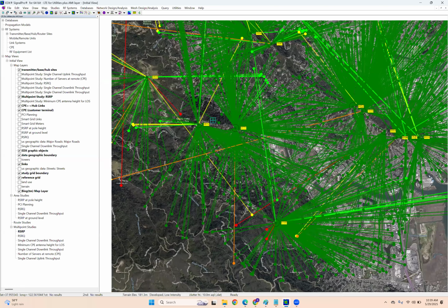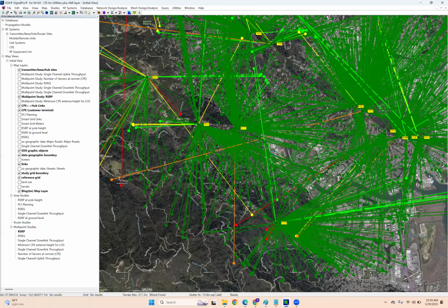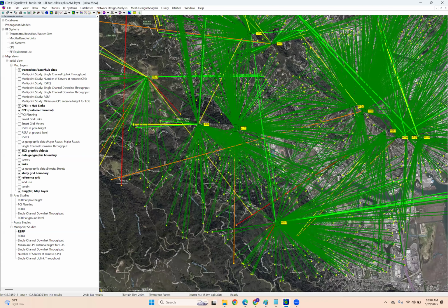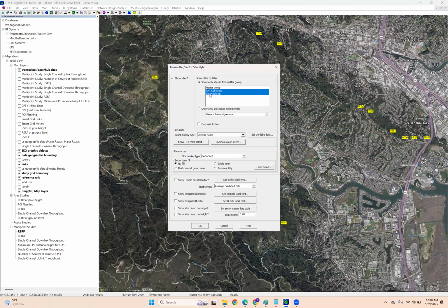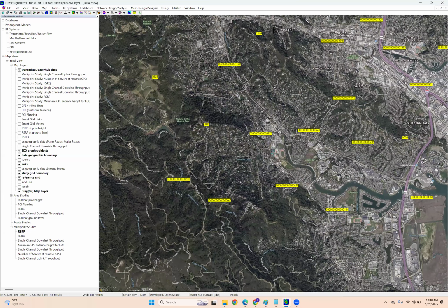If I've got an existing point-to-multipoint distribution automation project and I want to ask, can I add my AMI collectors in as endpoints on this LTE network? Well, what I went ahead and did was to first model out the AMI mesh. So if I switch to show my AMI collectors group, here are all of the collector sites for that 900 megahertz AMI mesh.